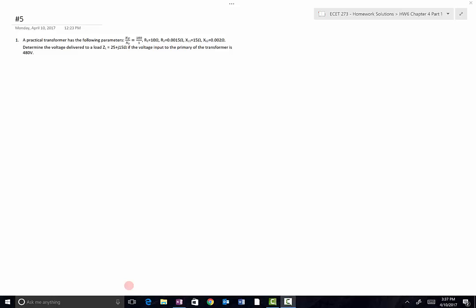So this is the first homework example that deals with practical transformers, where we're modeling the phase shift caused by the transformer coil, the power loss caused by the transformer on both the primary and the secondary side. So the givens in this problem statement are obviously the turns ratio, NP to NS, 100 to 1, a step-down type transformer. We've got the primary core resistance R1 equal to 10 ohms.